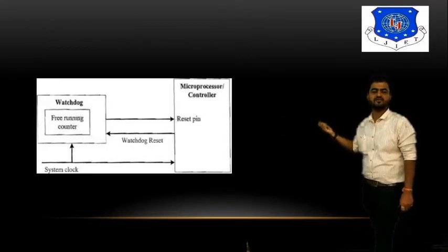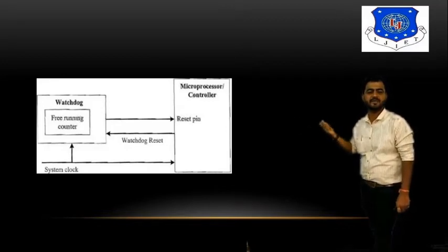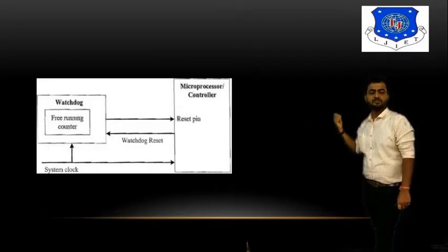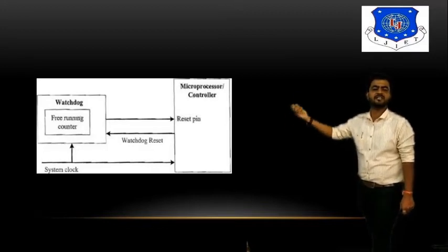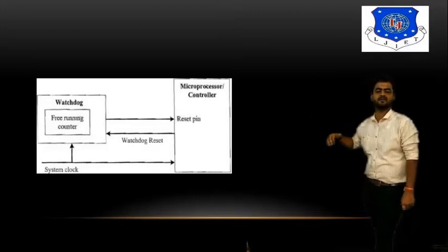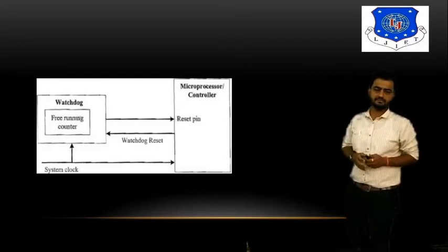So what exactly is the role of the watchdog timer? It will match with a reset pin. If the counter reaches the maximum limit, then ultimately it will trigger or provide the pulse to the reset pin, and the reset pin generally resets your whole microcontroller and microprocessor.